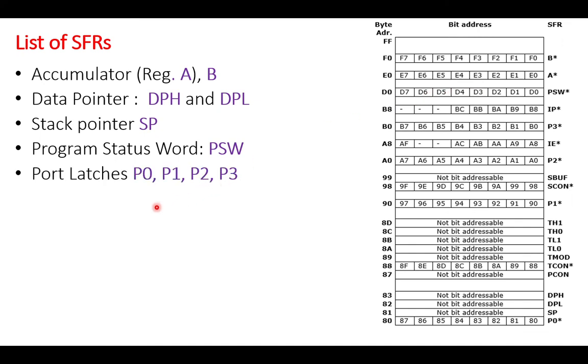There are 4 8-bit ports in the 8051. They are named port 0, port 1, port 2, port 3, and they are bit addressable. You can view that port 0 has address 80. Particularly, the P0.0 bit has the address of 80, P0.1 bit has the address of 81H, P0.2 has the address of 82. That's why these addresses are written in brackets.